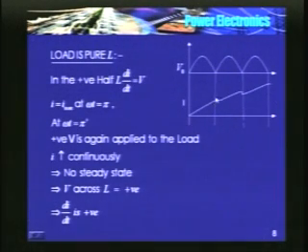So, current again starts increasing, whereas in half wave rectification from pi to 2 pi, the voltage appearing across the load was negative, that is why di by dt becomes negative. Whereas in full wave rectification, it is positive voltage appearing across the load beyond pi, so current again starts increasing. Please note, it is not linear, again increases, and so on.